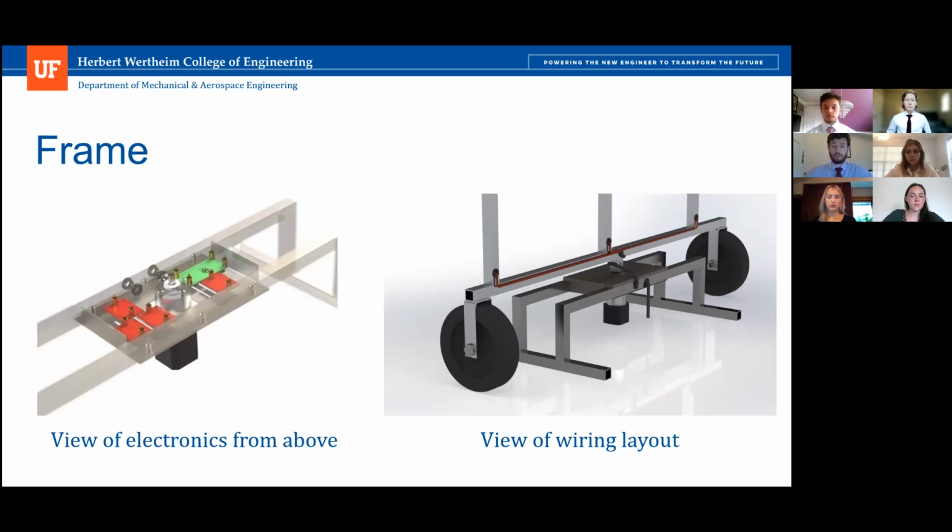And so for the wires, we're using 26 gauge wires. And for the top motors, since the control platform is rotating, we're wrapping the wires for all 3 motors in a wire loom and putting that around the shaft coupler. So the image on the right gives a representation of what it would be in the most extreme state. So this would be after it's rotated 180 degrees to track the sun. And then at this point, we would need to use computer software to tell the module to rotate the other way so it doesn't keep wrapping the wire.